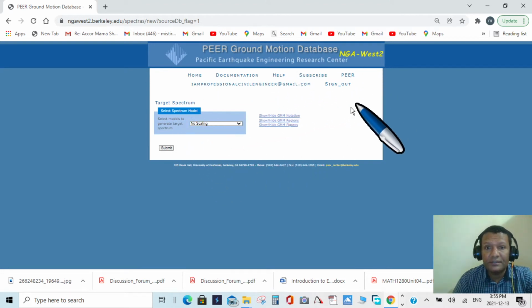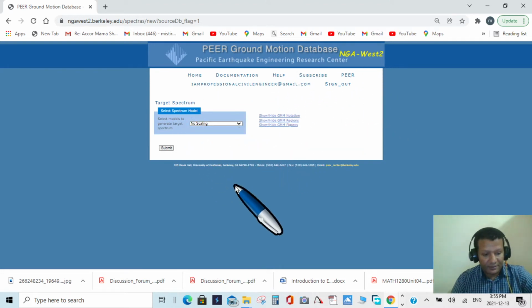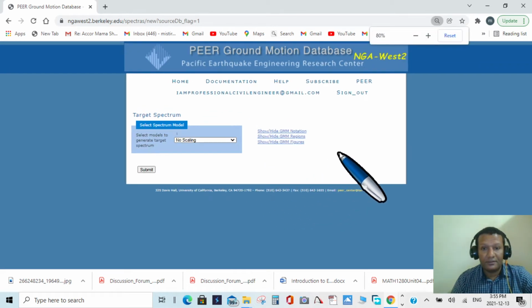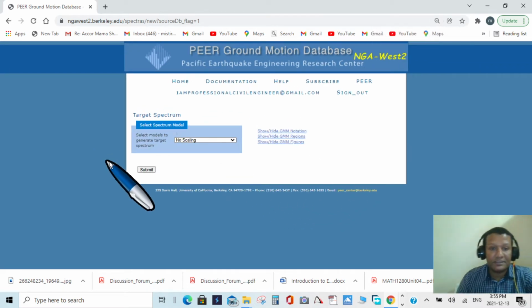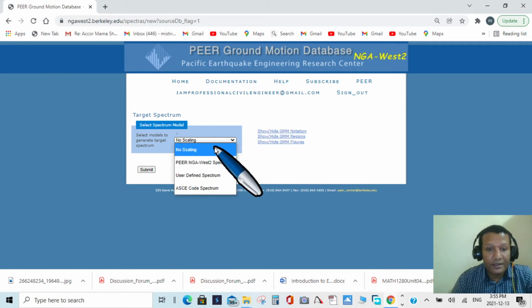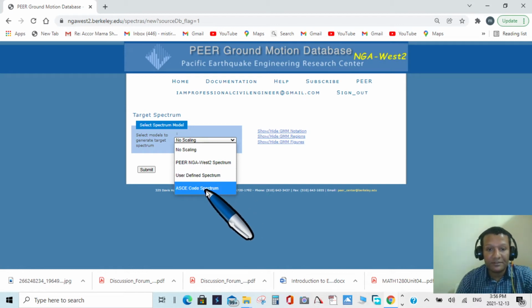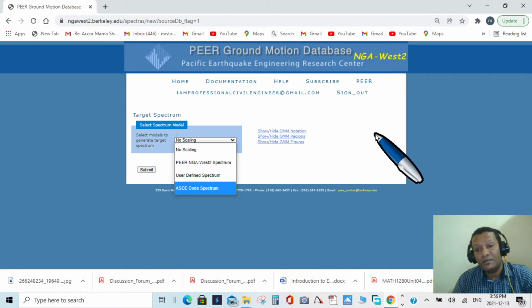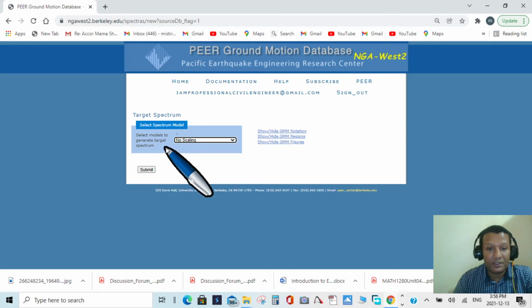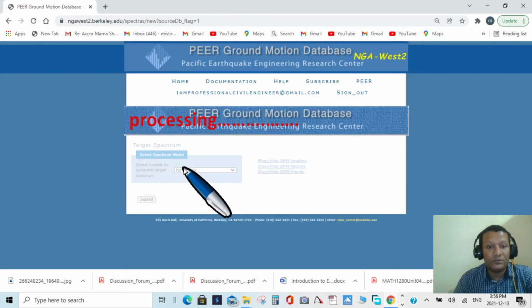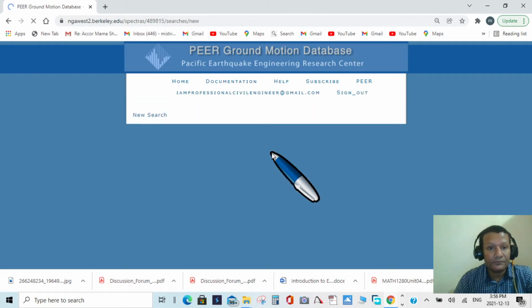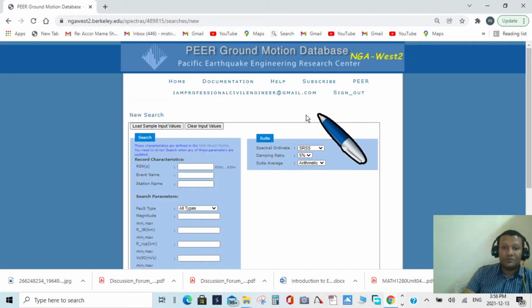You can choose no scaling, PGA, a target spectrum, a user-defined spectrum, or the ASCE code spectrum, whatever you need. But for our demonstration, let me go to no scaling.